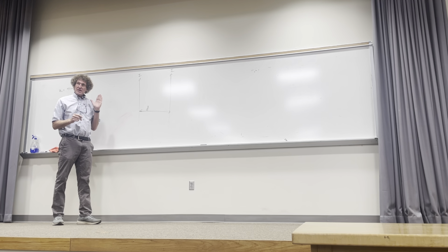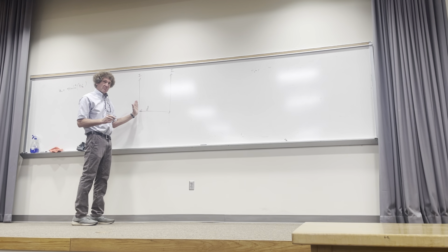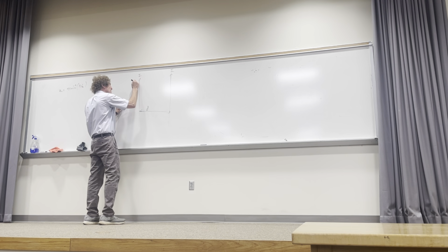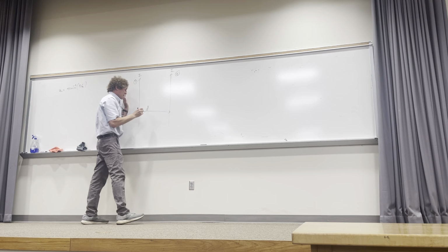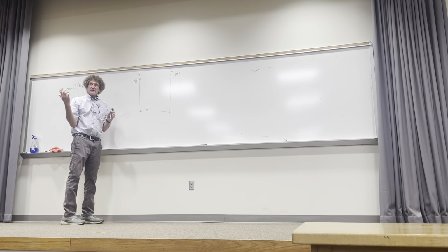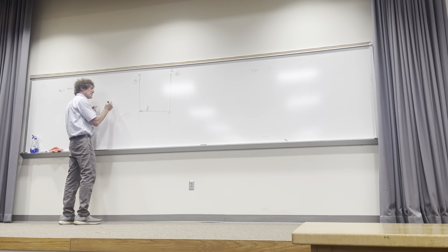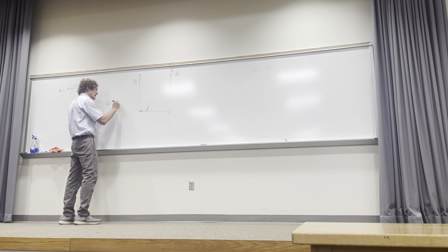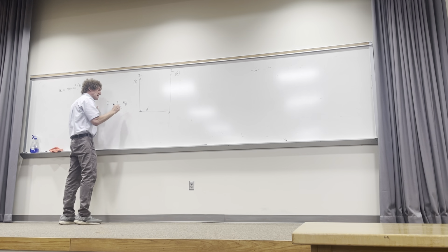Now, if you think about just the magnetic field caused by this, I'll call this the first current source and this the second. The way I like to think about this, the H field in general from any infinitely long current is I over 2 pi rho, where rho would be the radial distance, and it would be circulating in the a phi direction.